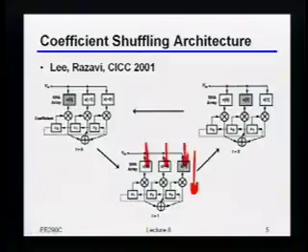Chris? Oh, whenever you switch multipliers, there's a charge sharing for the capacitor. Okay, that's right. There are actually some glitches and things like that you have to worry about. That's actually a very good point. We'll see that in more detail in a second. Shiva? You have so many switches and clock routing. There we go.